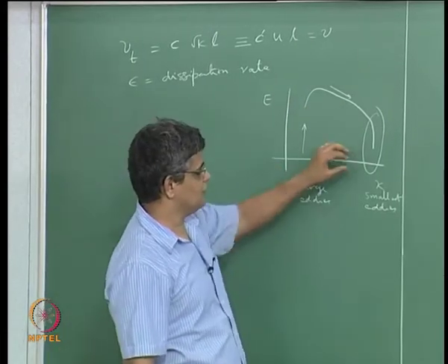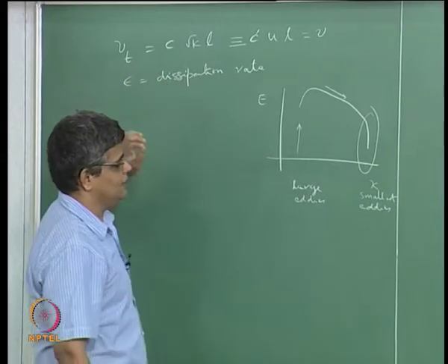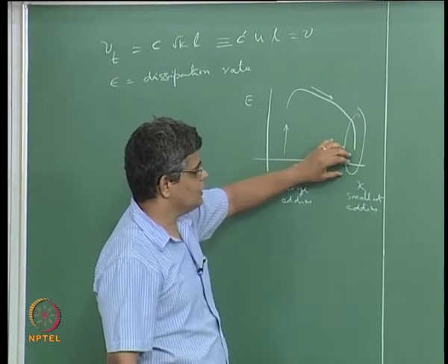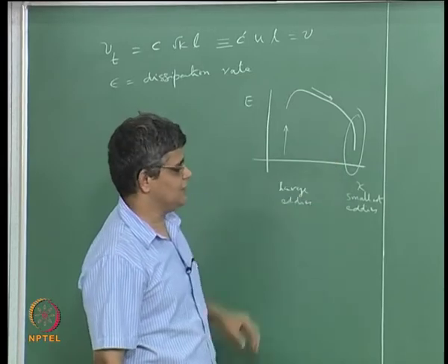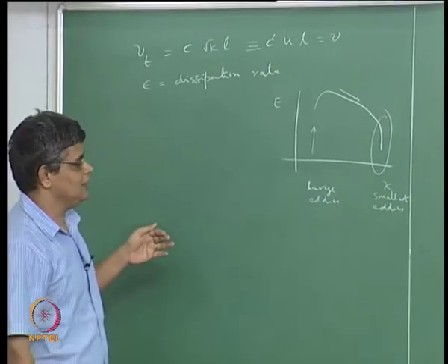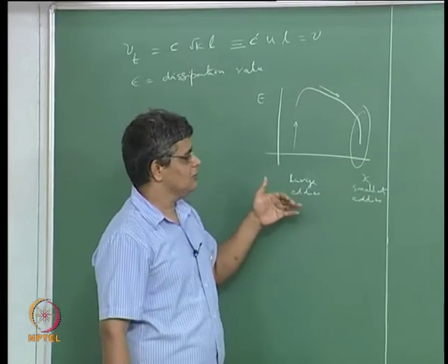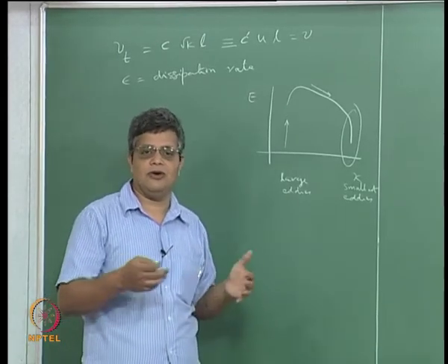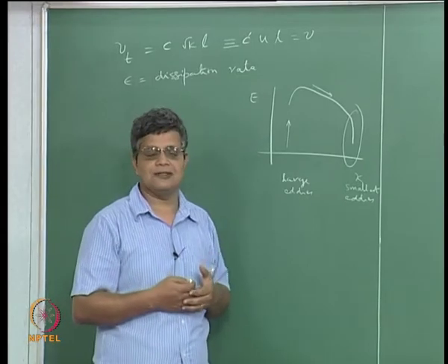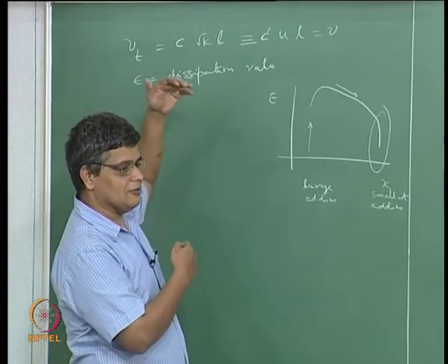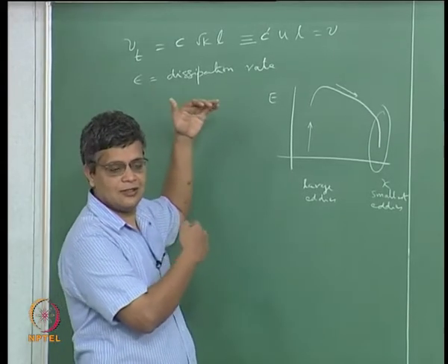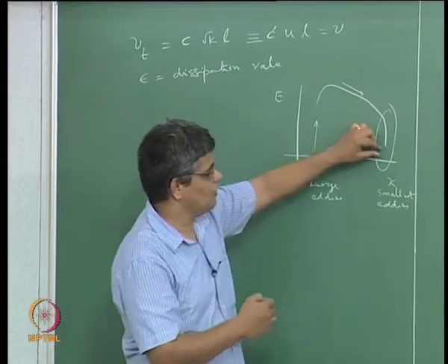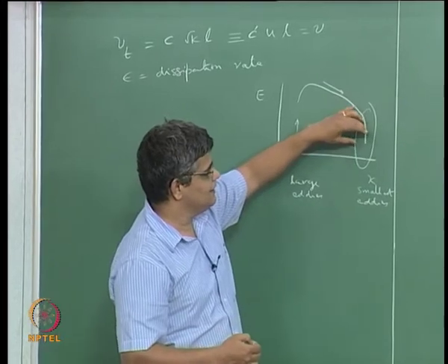So this is a key feature of turbulence modeling, especially that the turbulent energy dissipation happens at the smallest eddies of the length scale associated with turbulence, and these are so small that they do not know whether the turbulence is created in a flow in a circular pipe, or in a boundary layer, or in some mixing region or anything like that. Those scales associated with a circular pipe or a boundary layer or with pressure gradient and all those things are very large compared to the small eddy scales, and this is independent of the geometry.